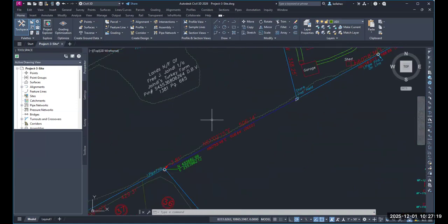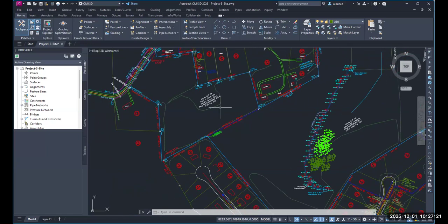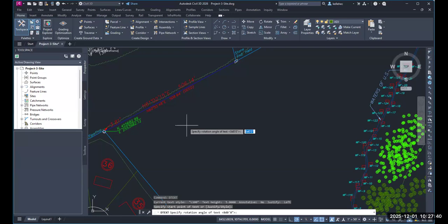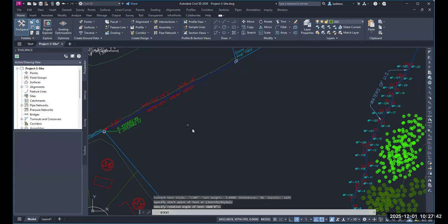For instance, your trees over here, you might keep trees, but you're probably not keeping the entire area. So be sure that you are focusing in and creating your own layers, especially if you're keeping a large part of your site as trees. Make sure to draw those, make sure to annotate it, make sure to add text. As a reminder, dtext, specify the point, specify the rotation, and we can get text from there. Enter, escape. Mtext also works.